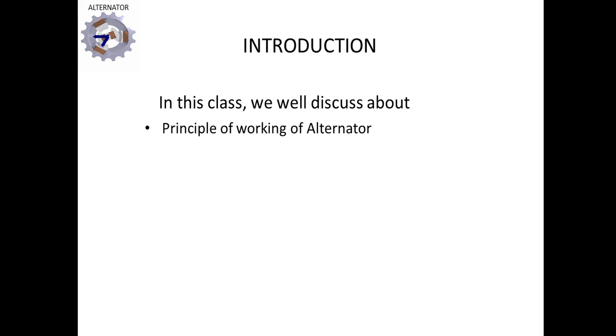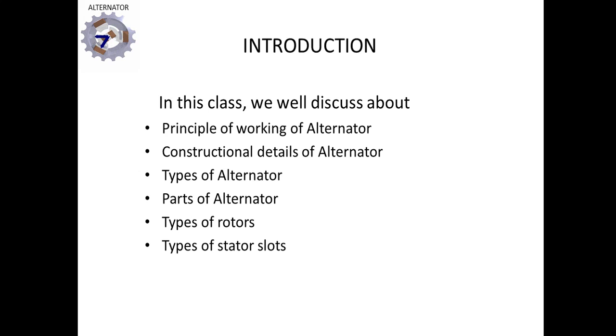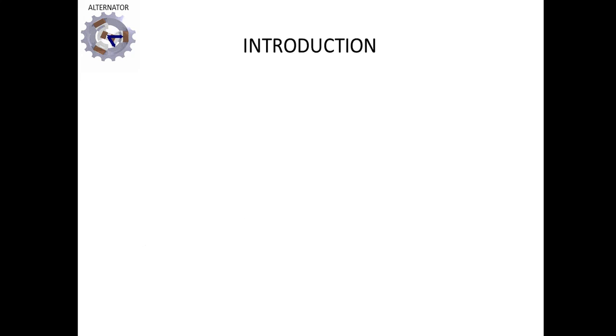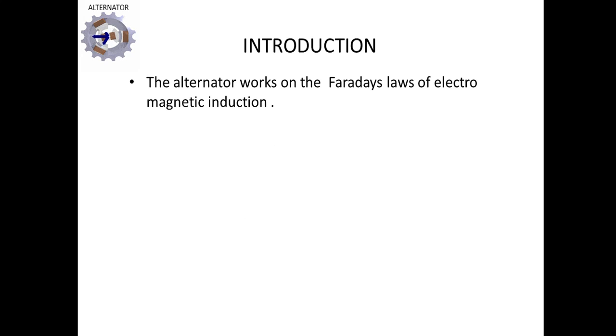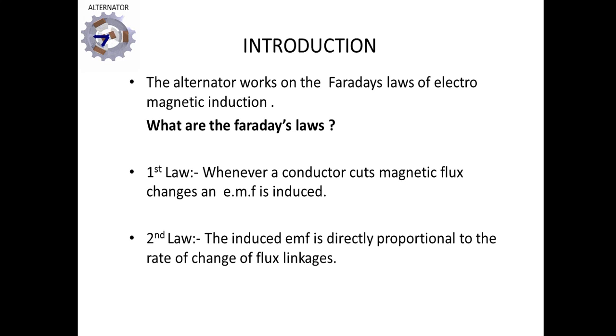So in this class we are going to learn about the principle of operation, construction details of the alternator, types of alternators, parts of alternators, types of rotor, and types of rotor and stator slots. Here the alternator works on Faraday's laws of electromagnetic induction. The first law states that whenever a conductor cuts the magnetic field, an EMF is induced. The second law states that the induced EMF is directly proportional to the rate of change of flux.